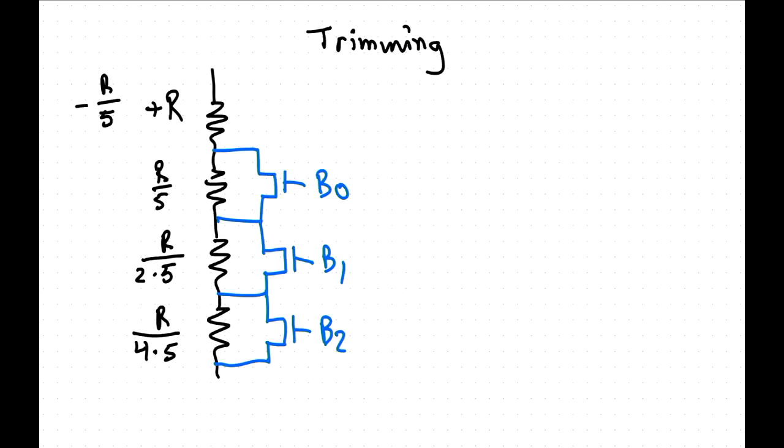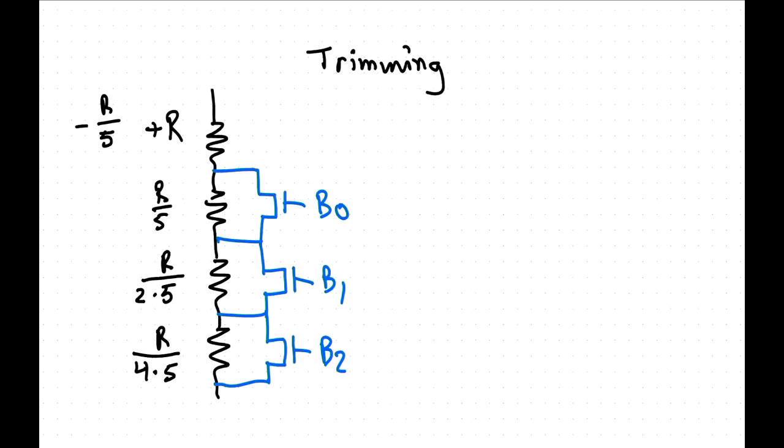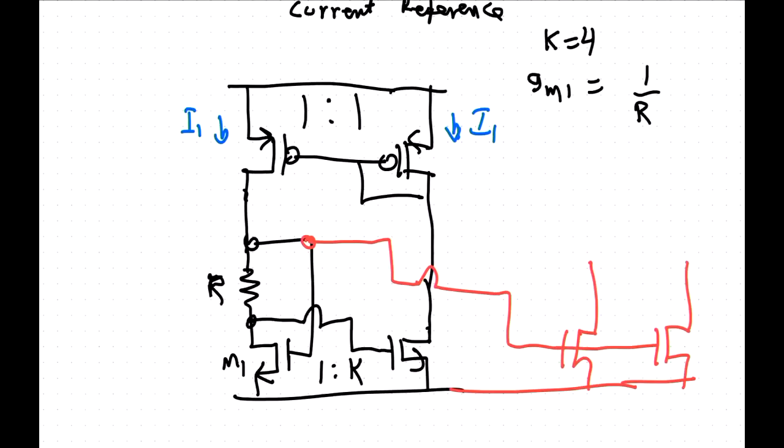All right. Okay. I should say on your op-amp, normally you just live with the process variation. Sometimes the biasing circuit is even just a resistor to the power supply. It's pretty simple, but it does mean that the variation in the op-amp performance is actually very large.